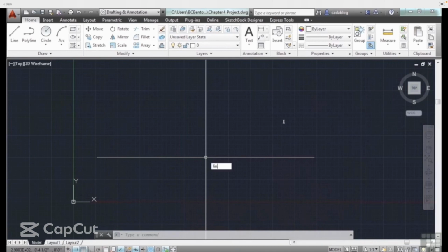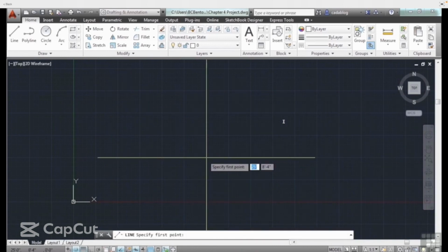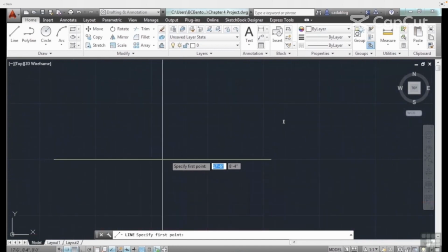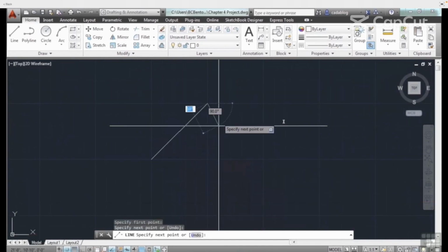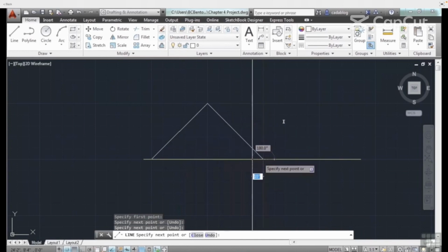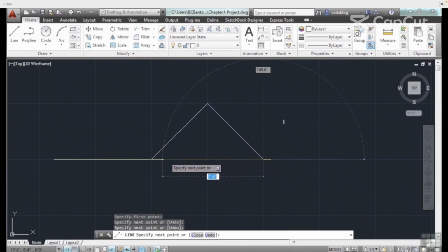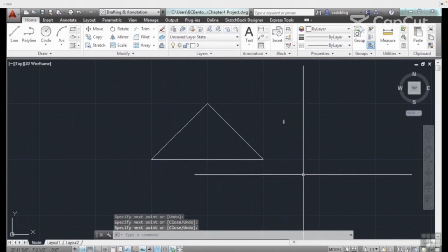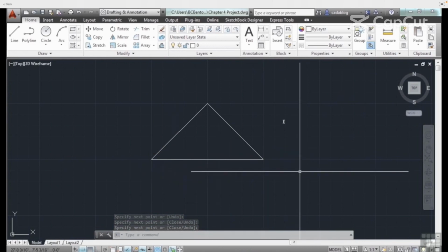Now let's start drawing a line. Let's type line on the command line. Press enter. Let's draw a triangle. Now remember that we're snapping to specific places on the grid. That can help us line up our lines very easily. So pick a point, snap, snap again, and then just snap to the end. There's a triangle. See how easily the snap function allowed us to work?